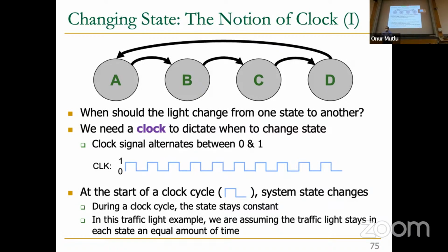So I have 0.1 nanoseconds to finish work and then go to the next state. So you cannot have any combinational logic that takes more than 0.1 nanoseconds, because if you have it, the results are not available when the clock changes. If the result is not available, that combinational logic is useless. Well, it's actually wrong. It computed something that you couldn't capture. Again, this will become more clear when we talk about timing and verification.